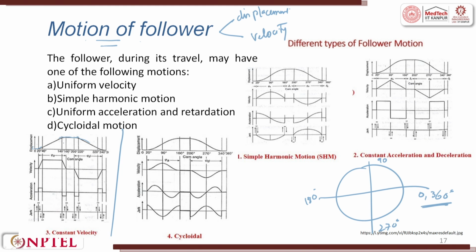Okay. This is the displacement. When I take the displacement divided with respect to time, I get the velocity. You can see a uniform velocity; the velocity is the same. Then when it hits the dwell, it falls down. So, the rotation happens, right. The first half is up to 180, and then from 180 to 360 it falls down. So, this is displacement, and here you have velocity.